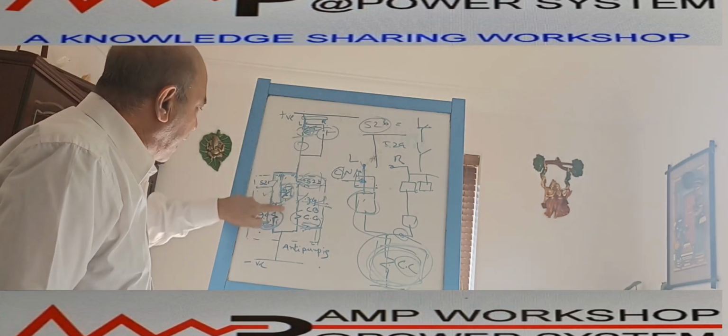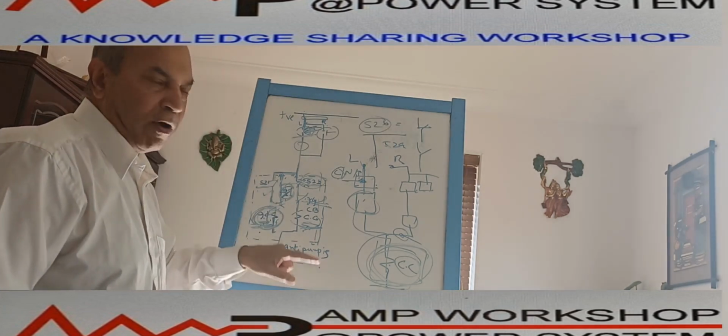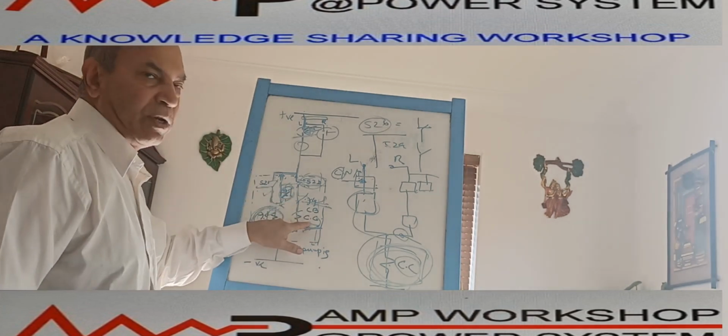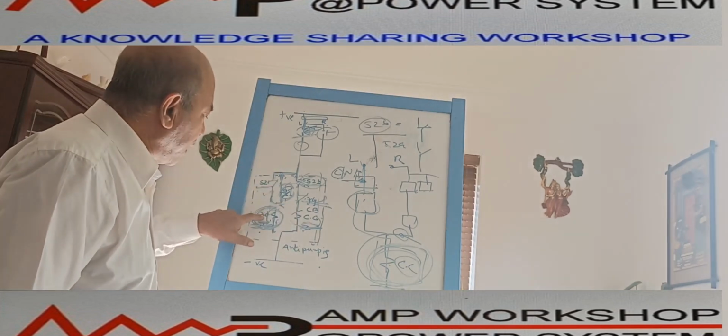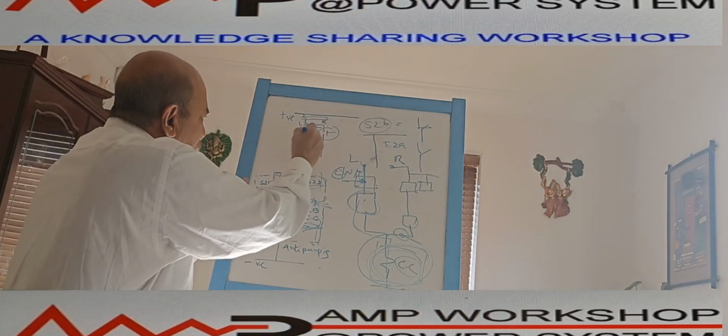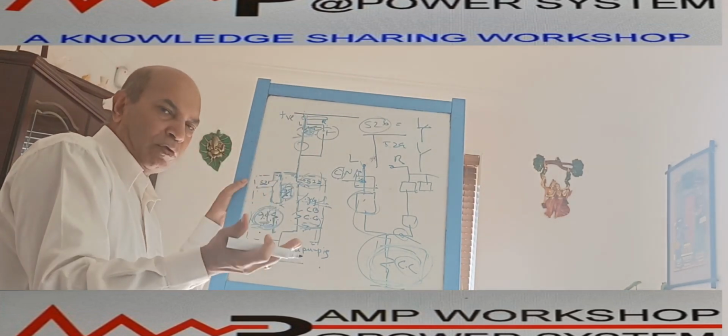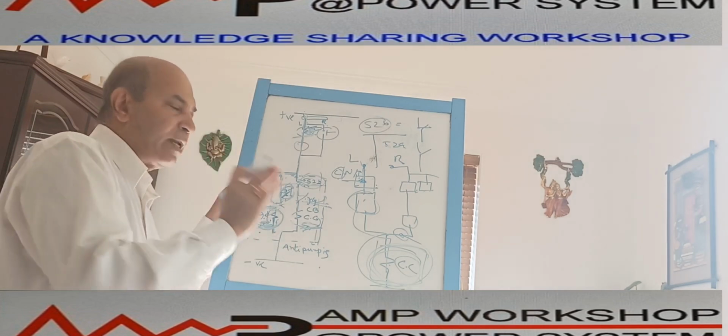At that time, if you maintain the command over here, what will happen? As this anti-pumping relay is energized, even on a fault, suppose on the fault the breaker got tripped, okay? The breaker got tripped, but the anti-pumping relay is not getting tripped. If you maintain the closing command when there is a fault, the breaker gets closed, but you are still maintaining the closing command.